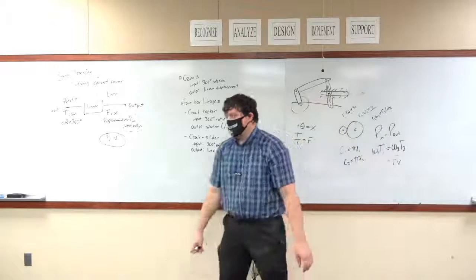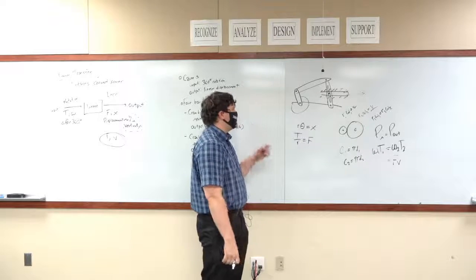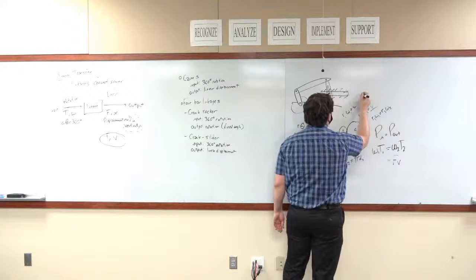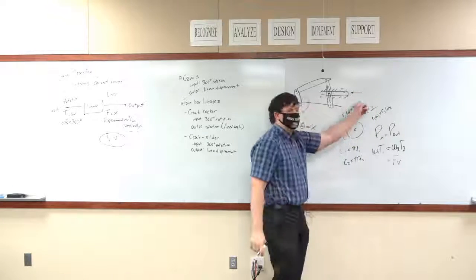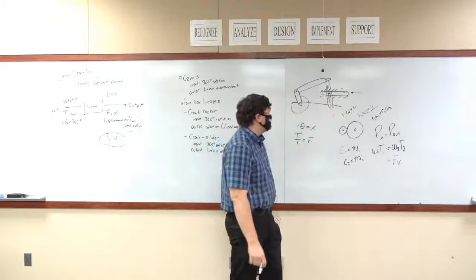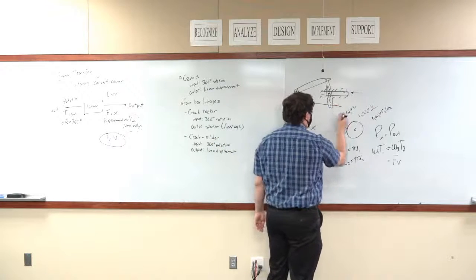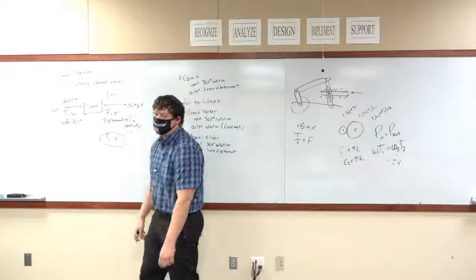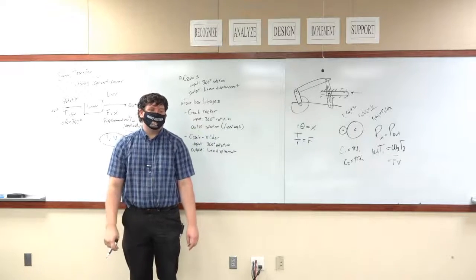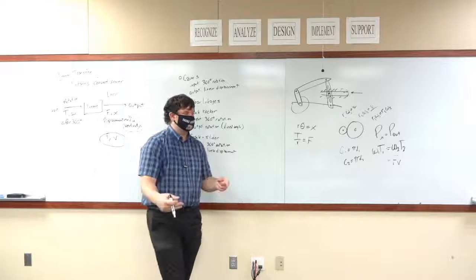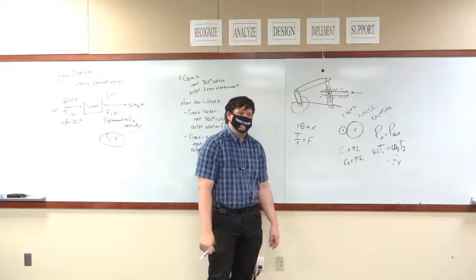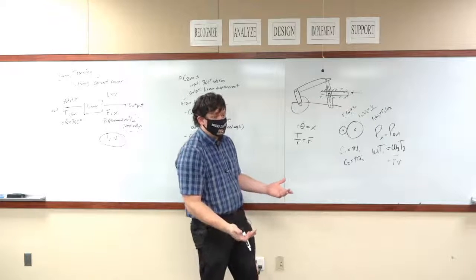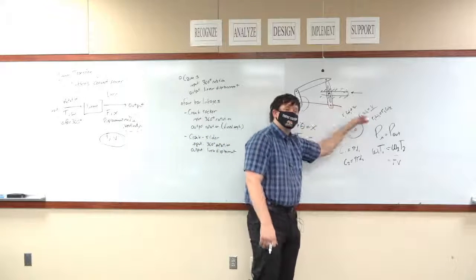Now, when I said this is better than a crank rocker system, applying a force here, let's say this was your leg mechanism. If you apply a force here, that force is carried in part by this pin. You do not have the perfect 1-to-1 ratio of force input going straight into the crank. Okay? You do have some help in resisting movement in this direction.